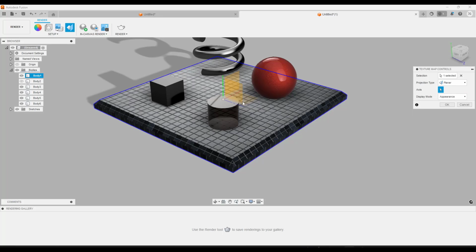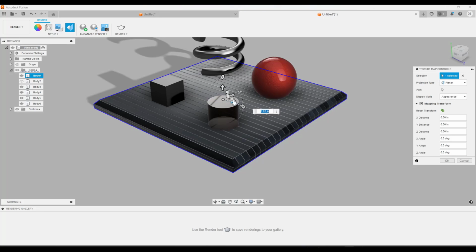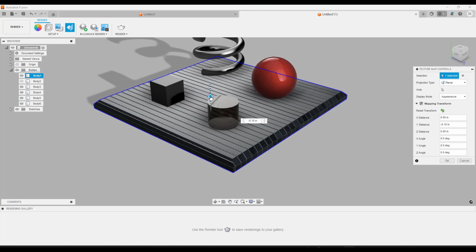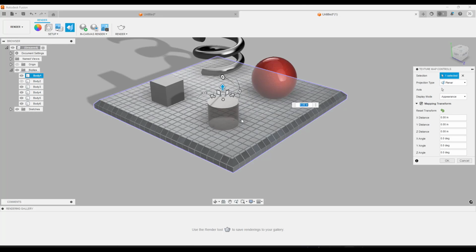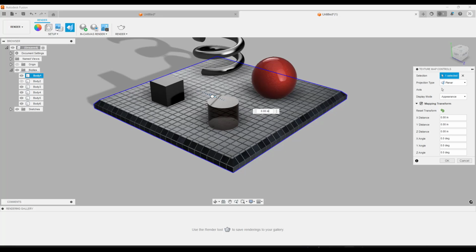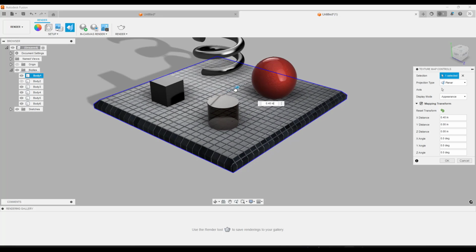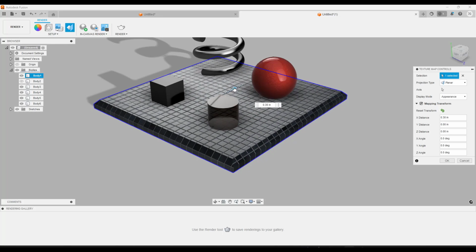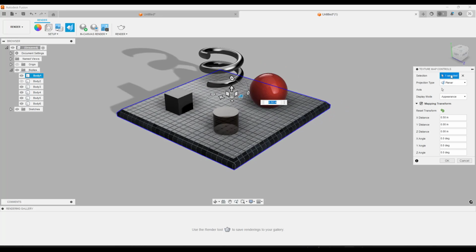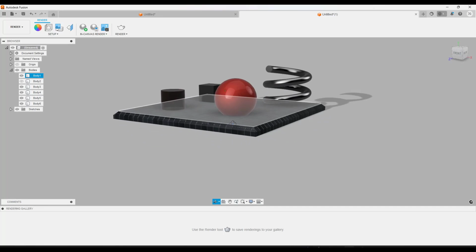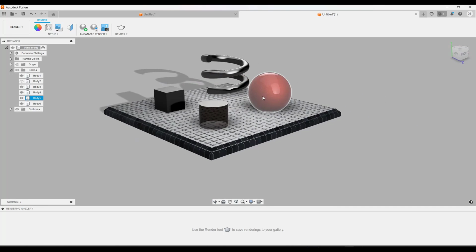And there's a planar option, which you can use to set the plane direction of the materials like this. That one's not always going to do what you want it to do, but notice how you can play around with this. The planar is going to set if this is mapping this straight up and down, or how this is placed on here, and then you can use the arrows to adjust this. So you're going to want to play around with this until you get a mapping that you like, but a lot of the time you can use these texture map controls to make your materials map onto a surface a lot easier.